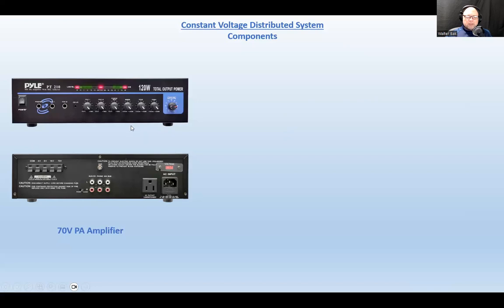Also, I'm going to mention that some amplifiers, and I don't see this one having it, would have relay contacts here. The purpose of that relay contact or dry contact is that you connect a relay, let's say the relay that is part of the telephone system, to close the contacts for the channel, the microphone or the audio channel, to operate.